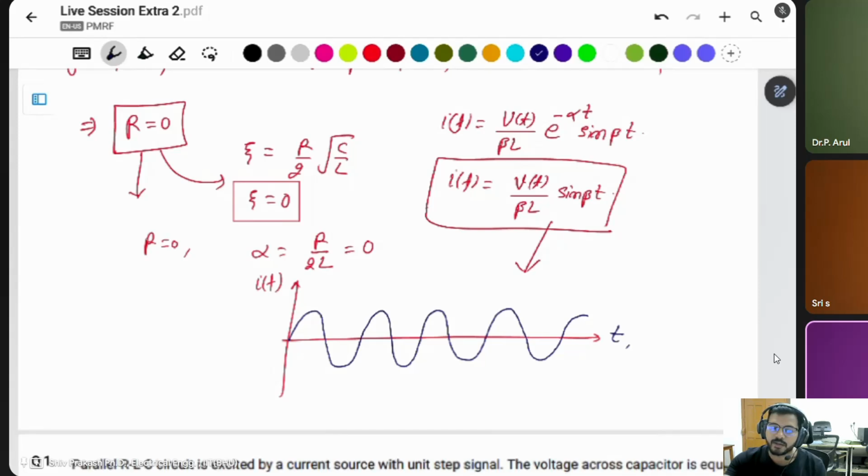In that case, the thyristor is not turned off by the DC source or by natural means. Instead, you use an LC commutation circuit to turn off the thyristor in a DC source. The LC circuit makes the current negative, and a negative current never flows through the thyristor. That's why the thyristor will be turned off. This is known as the force commutation process of the thyristor. The same circuit is used to turn off the thyristor.